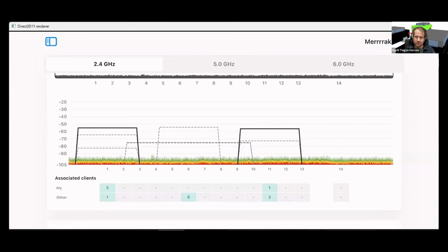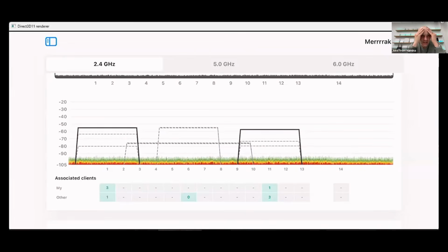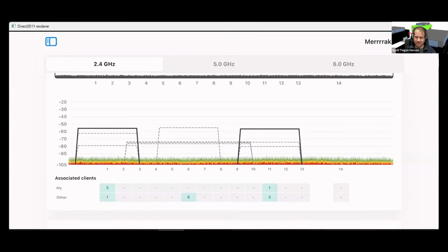It works great. But on Uni 1 and Uni 3 you can generate a lot of different signals, and it won't react, because it doesn't look for radar. There you can generate a lot of things, but usually, depending on RRM technology, it will still move away. Yeah, exactly. I had a Meraki access point, and I did a microwave video once, and my Meraki access point always changed channels when I turned on the microwave. I got so disturbed that I had to use another access point that RRM worked worse on, because the Meraki always changed to channel 1 because of interference on 6 and 11.